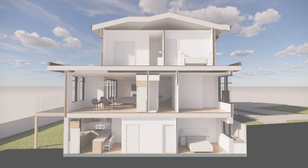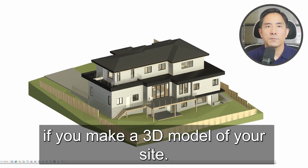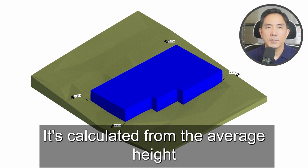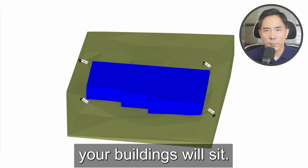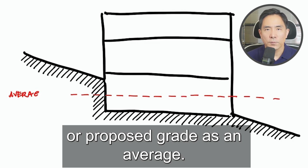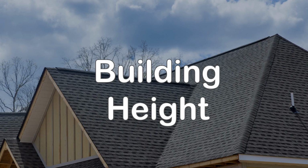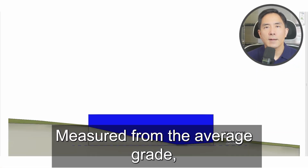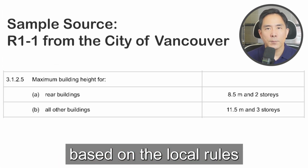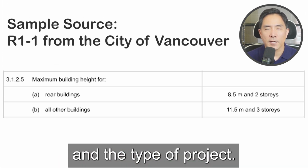Average grade. This is something easier to visualize if you make a 3D model of your site. It's calculated from the average height of the four corners of where your building will sit. We use the lower of the existing or proposed grade as an average. Building height. Measured from the average grade, this is how tall your building can be, which can vary based on the local rules and the type of project.